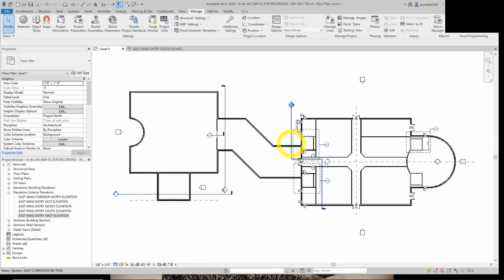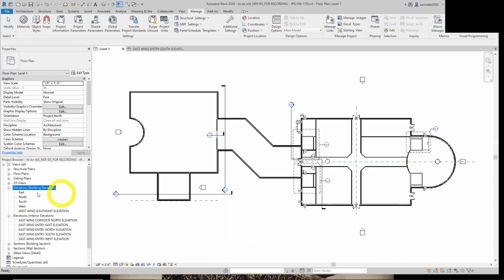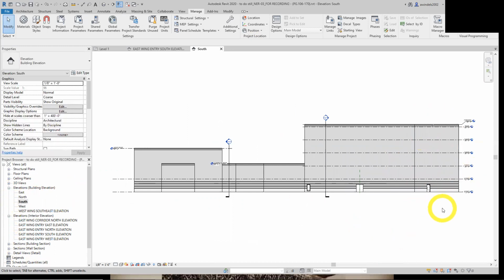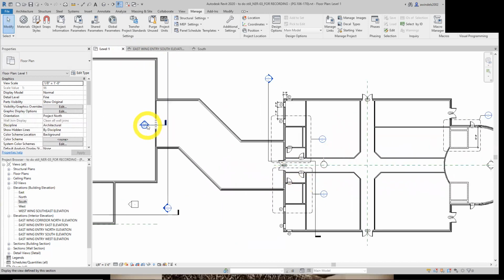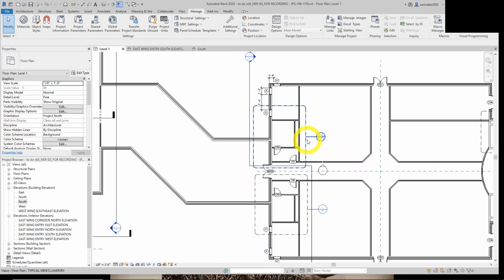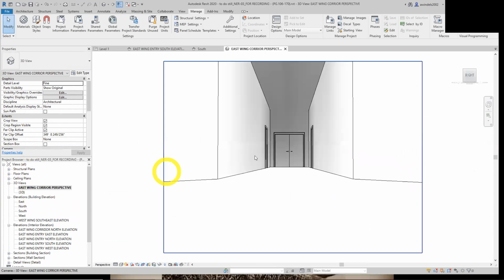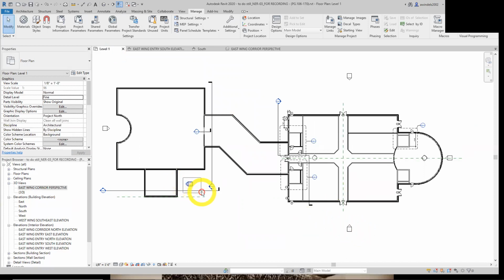We're just adding a lot of different views to control or model how our drawings can be laid out, detailed views. We learned a lot about creating levels, which is very critical, especially in elevation views. Go back to the south one, making them a multi-story building, controlling them where they go. And building sections, cutting through for different section views and detail views, very specific areas like here, and call out views, area to crop to and annotate to in tighter sheets later dynamically. We added cameras, perspectives, very specific areas to views, and we learned a little bit about interior and exterior elevations and adding more of these, to show really specific areas of our model that have a high level of detail, like these areas.